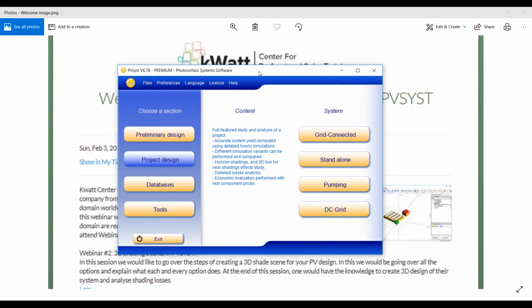Say, for example, you have a system already done, a ground mount fixed-tilt system or a single axis tracker system. It's always good to have a complete shading analysis done through PVSYST. In general, what we do with PVSYST is we take all the details from the layout, say, for example, module type, module tilt and things like that. But we don't do a complete shading analysis. We just enter those details, we just say how far the modules are, and then we run a simulation.